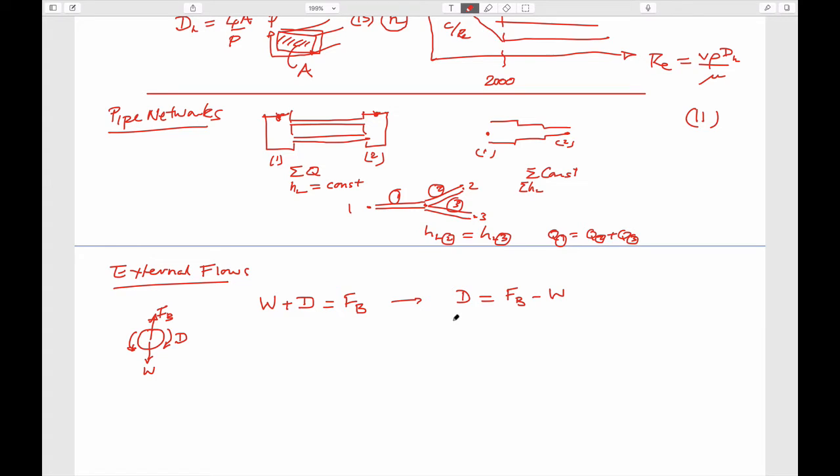And we can define the drag in terms of a coefficient of drag, which is equal to a drag force divided by a half, just by convention, rho v squared times A, which is the same as, if you split it out, a half rho v squared, with drag over area, this is basically a pressure.